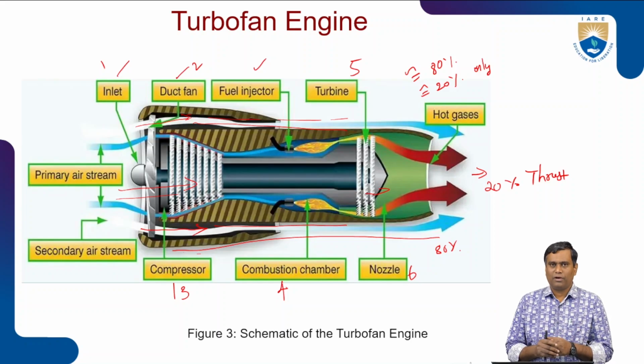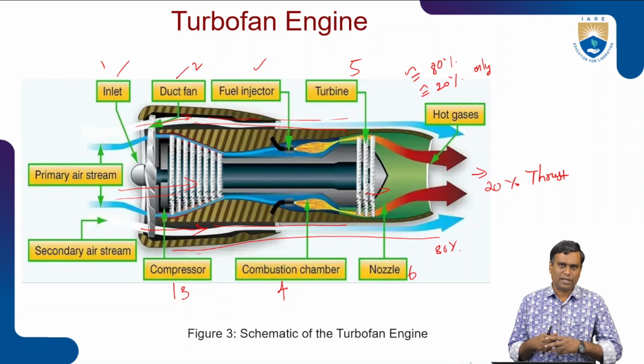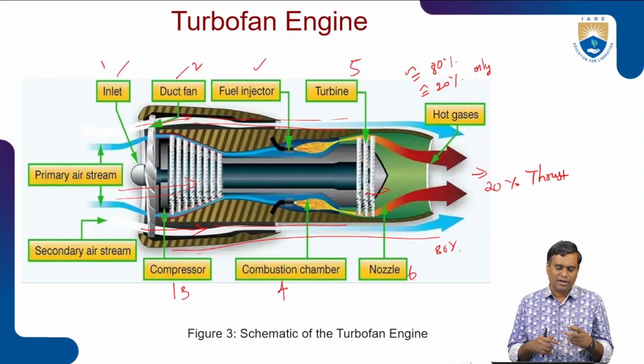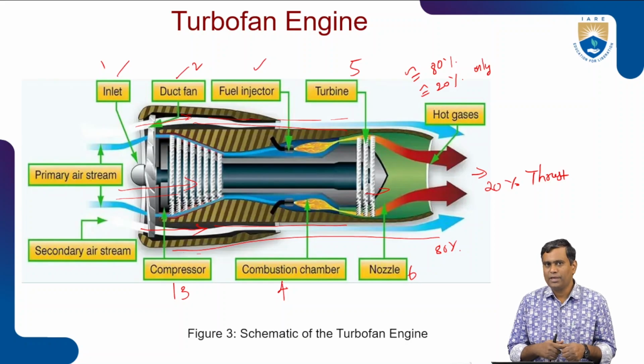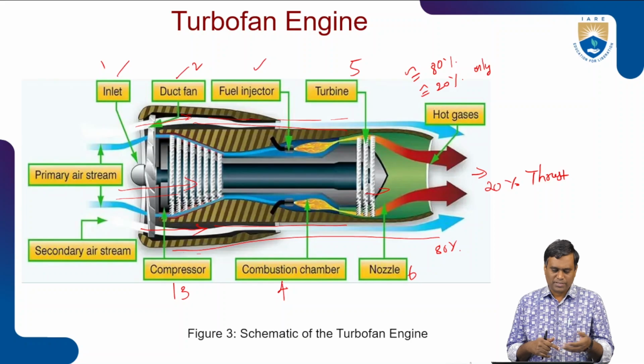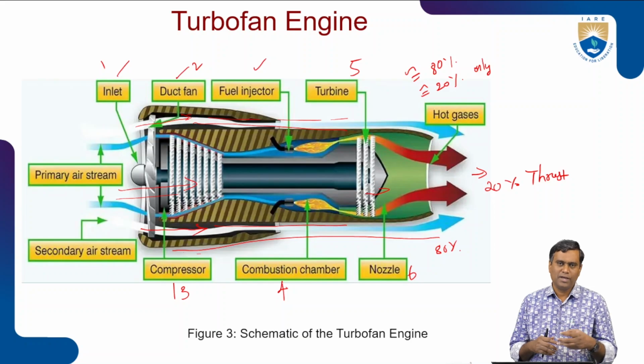Even though the RPM of the low pressure turbine will be very high, if the fan operates directly at such a high RPM, efficiency will come down, performance will come down. Because this is similar to propeller blades, right? This fan blade aerodynamics will play a role in this. So for that purpose, most of the...